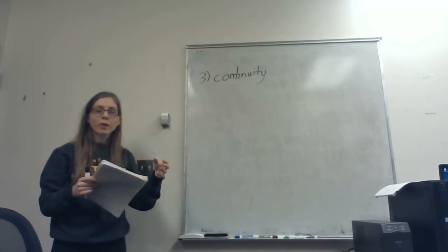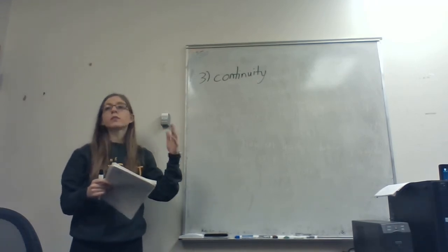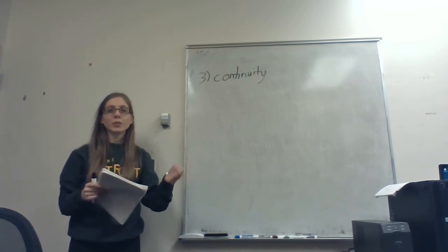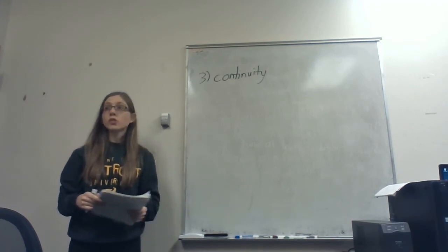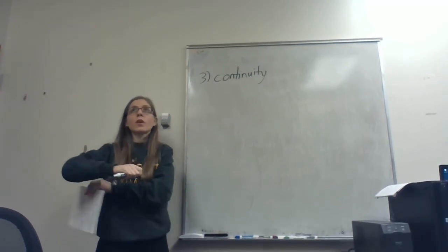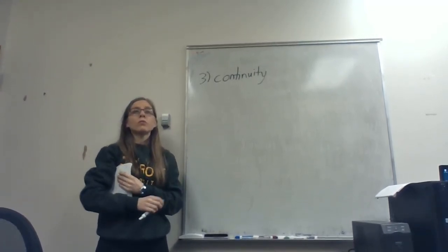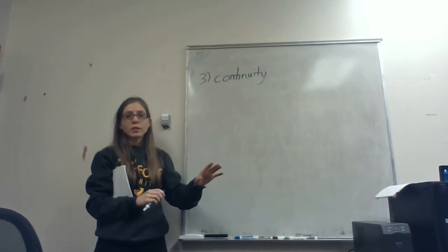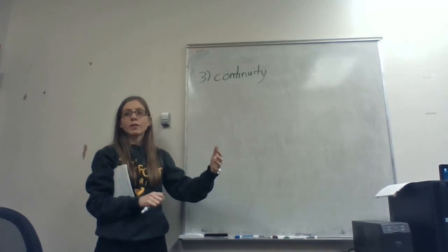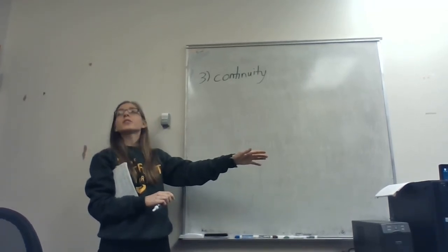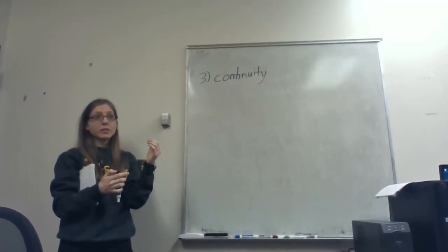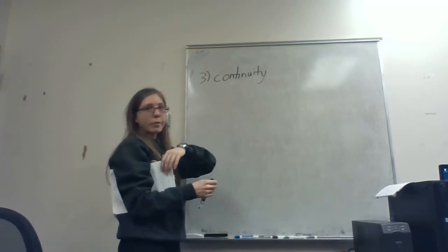Or if you have a slightly different parameter in your model, essentially with disturbances, your solutions remain similar to the one you would have got without that disturbance or with a different disturbance. Or else, again, it just goes crazy. Imagine the consequences of not having this: you make your model predictive controller, you predict, your model's off. Then instead of your solution being close, which is what we bank on in MPC, the solution would be completely different because there was a disturbance. Then this is not predictive for real life, and there are always disturbances in real life. So that's why this is important.